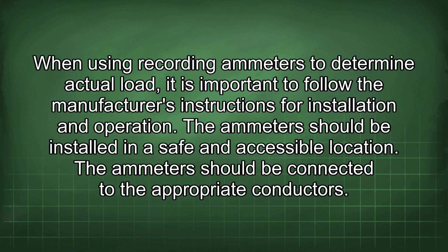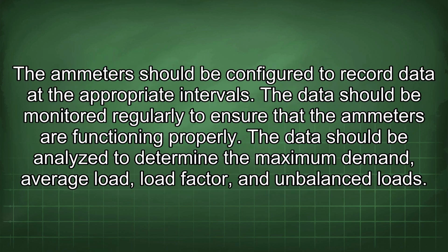The ammeter should be connected to the appropriate conductors. The ammeter should be configured to record data at the appropriate intervals. The data should be monitored regularly to ensure that the ammeters are functioning properly. The data should be analyzed to determine the maximum demand, average load, load factor, and unbalanced loads.